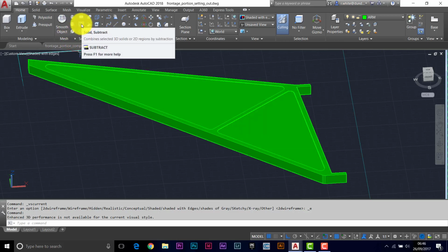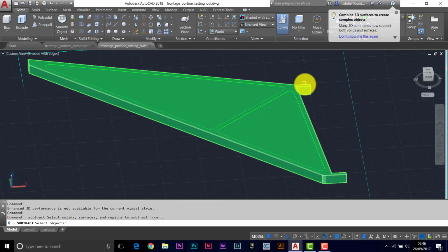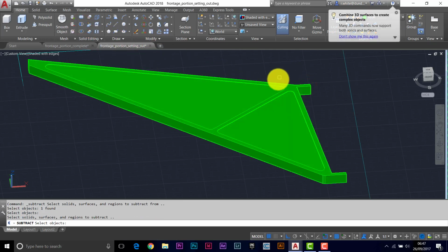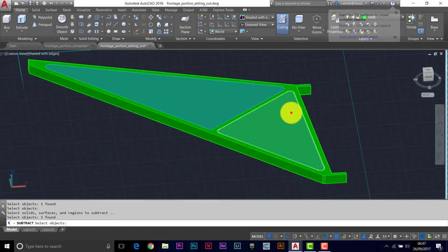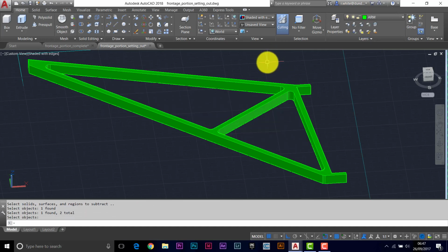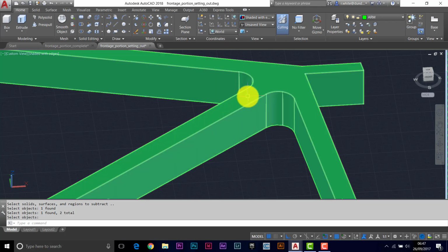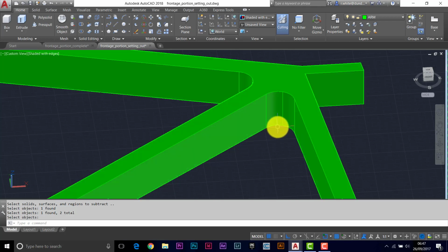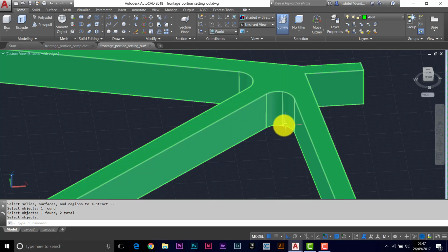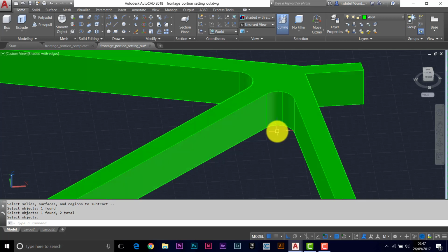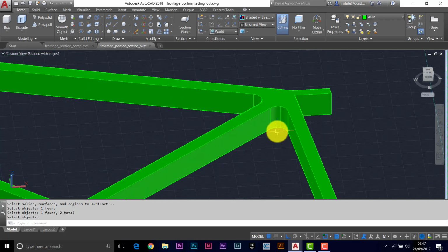Okay, what we want to do is subtract from the main shape, enter, then pick the two sub-shapes, enter. Get a very clean looking solid. Okay, the curvature here, we've left that, we've extruded the arcs. Now you've got to be aware that when that goes into something like 3D Studio, we have to watch that we don't end up with insufficient segments going around that curve. So we have to use a fairly high degree setting to make sure it still looks curvy later on.